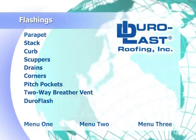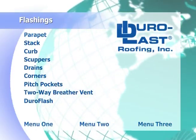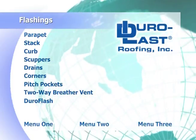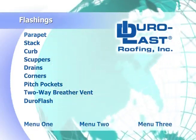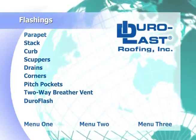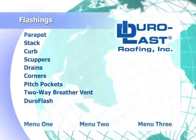This short video demonstrates the correct technique for using Duro-Last deck sheet membrane to flash parapet walls with tabs running up the walls. When extending tabs of your deck sheet flash up a parapet wall, it is recommended to not exceed 2 feet in height. It can be difficult to handle material if you exceed 2 feet.